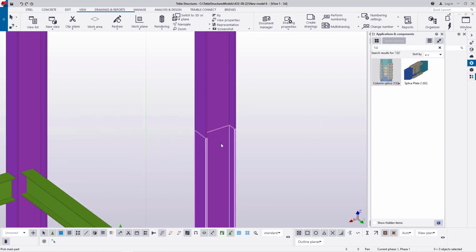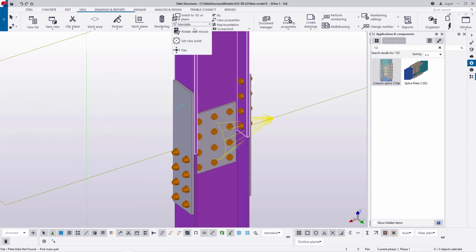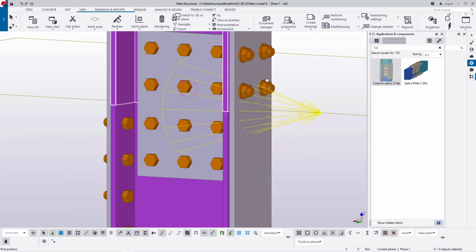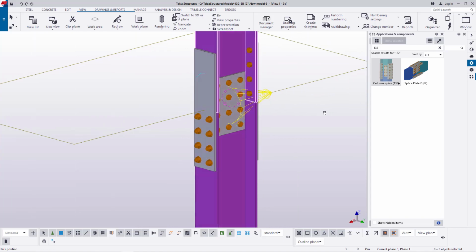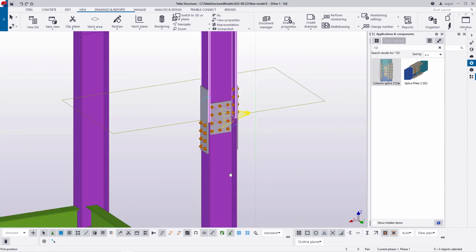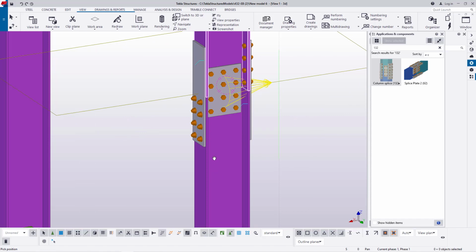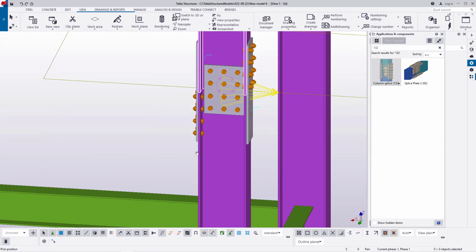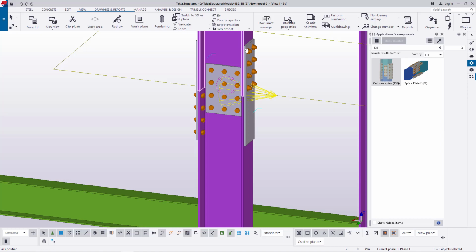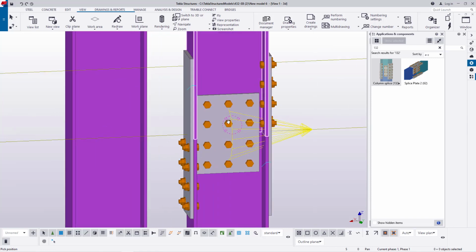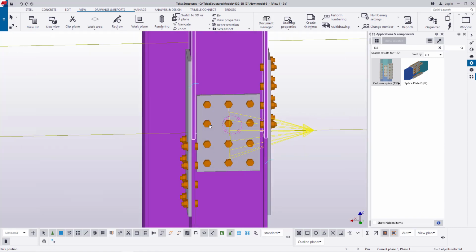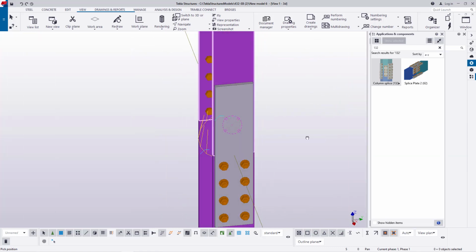So we want to connect this beam to that beam. So this is our splice joint. One part will be welded and the other section will be bolted, so that when you get to site you don't get confused in all this. So this part will be carried to site welded with this plate with the holes on that end, and the top side will be carried onto site welded with this plate with holes on this section. So this one, the flange will be connected with the plates on site.